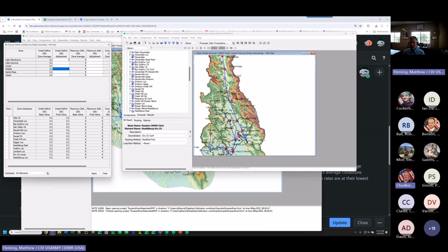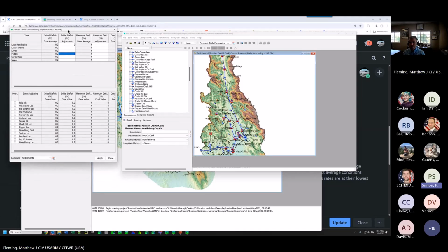Any comments about that approach? So Matt, maybe it doesn't matter, right? If you're just calibrating so you can get your inflows at the next reservoir at your next control point, but maybe if you're running RAS through one of those reaches, you might care more about what your locals are. For sure, yeah, that's a good point. If you want to get to a reliable inundation map, then you would want to spend more time on those tributary flows. Yep, that's a good point.